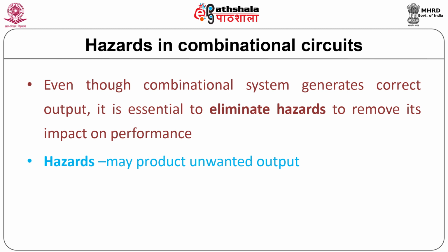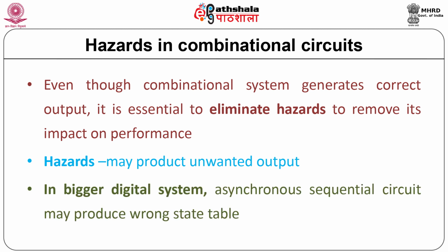In the combinational circuits, hazards will produce an unwanted output value. If such combinational circuits are used as building blocks of a bigger digital system like a synchronous sequential circuit, then it will produce a transition to the incorrect state table.